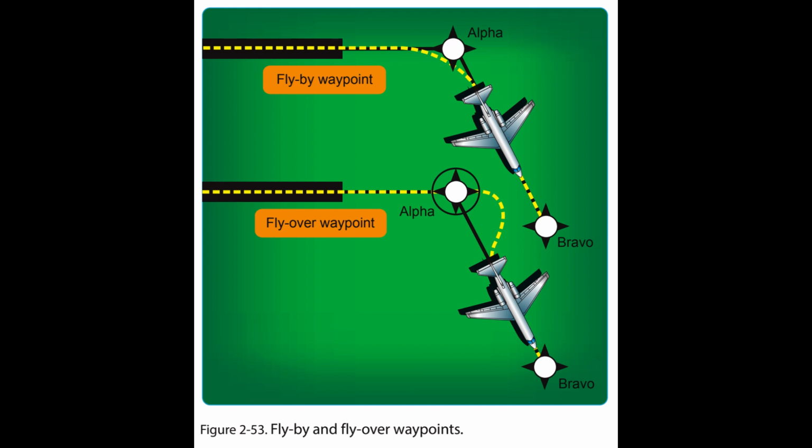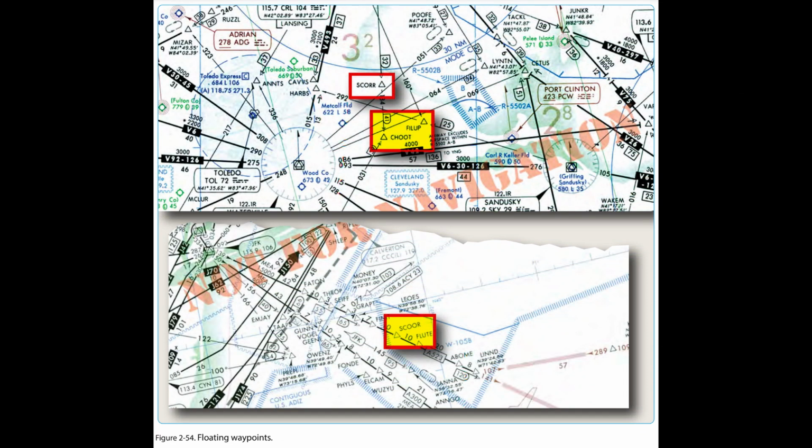All aircraft with latitude and longitude navigation systems flying above FL 390 must use latitude and longitude to define turning points. Floating waypoints, or reporting points, represent airspace fixes at a point in space not directly associated with a conventional airway. In many cases, they may be established for such purposes as ATC metering fixes, holding points, RNAV direct routing, gateway waypoints, STAR origination points leaving the en route structure, and SID terminating points joining the en route structure.